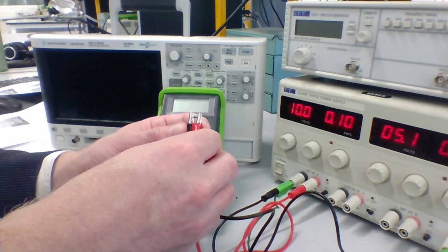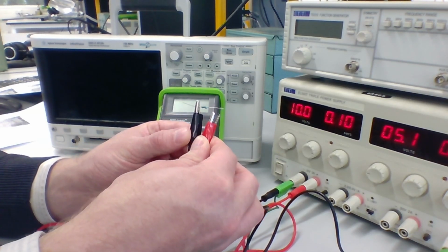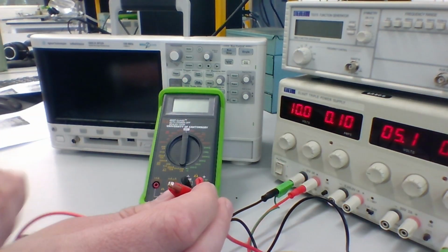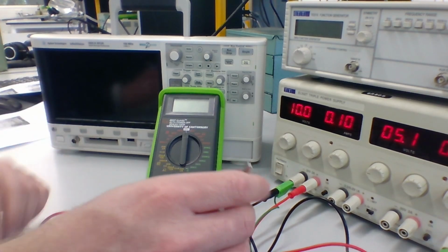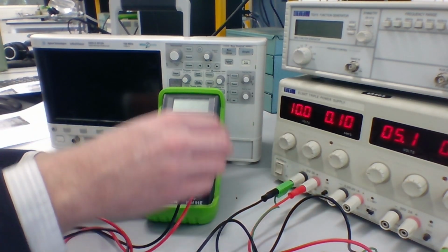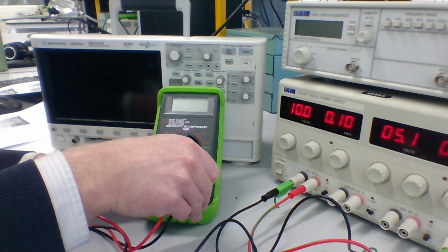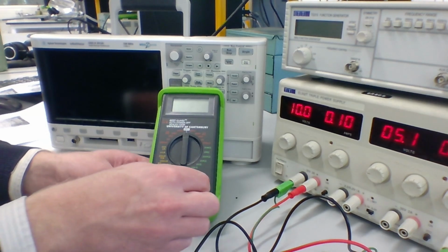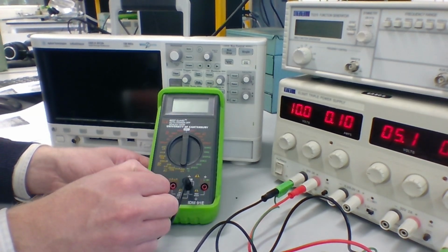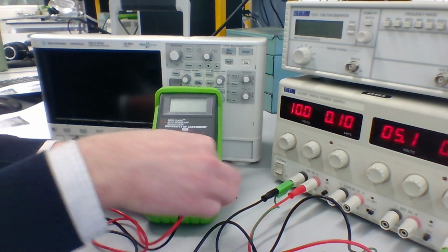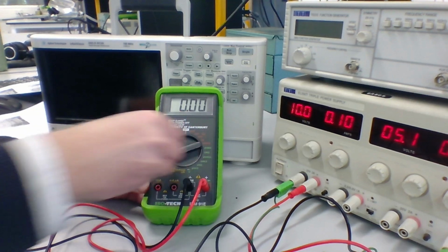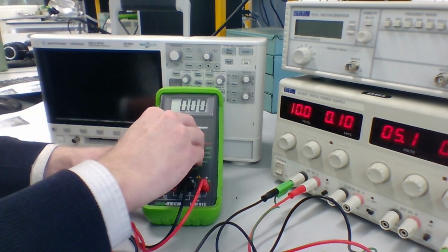What I'm going to do here is disconnect the positive lead of the power supply, and I'm going to connect that to the positive lead of the multimeter. But firstly, I'm going to change the multimeter connection so that instead of measuring voltage, we want to measure current. So we're going to change this to one of the 2 current ports here. If you don't do that and you start trying to measure currents, the multimeter will tend to beep at you or give you some kind of warning.